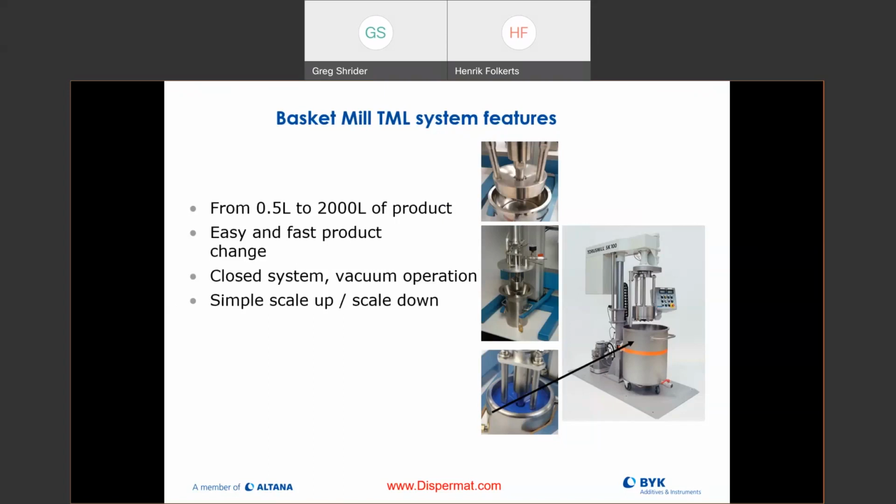So that reduces that. Imagine some of these foams, these air bubbles entrapped in my mill base, they act almost like tiny little air mattresses. They are buffering all the blows and causing inefficiencies in my milling step. If I can remove those, I have a quicker and more homogeneous milling, grinding. So there are also advantages through the milling cycle, as well as afterwards, my product transfer is improved because I don't have any foaming, okay?